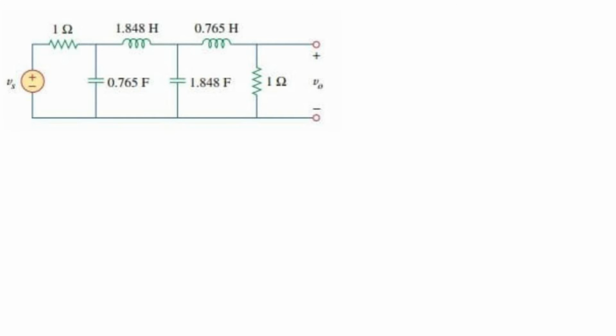Previously, Meimei stated that she wanted the frequency response to be shifted from a 1 rad per second cutoff frequency to 50 kHz. By that, we can calculate the Kf. Kf is the ratio between the actual frequency versus the planned frequency. By doing the calculation, we will get the Kf.